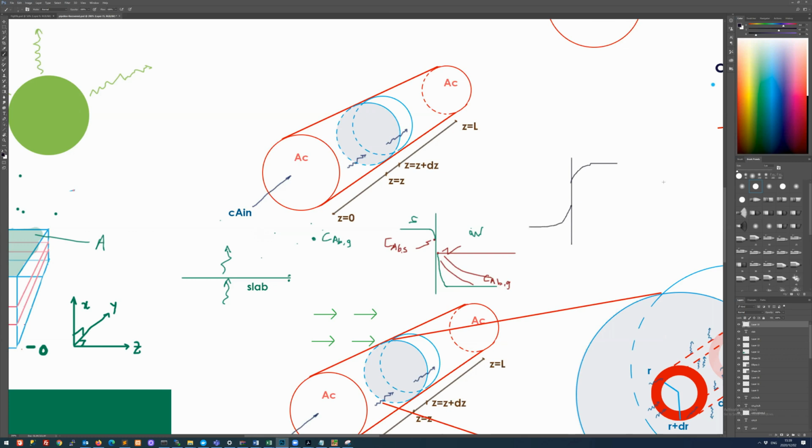So this is the position R, and this is going to be the radius of the particle. If you look at the particle, let's draw it here like this. R equals 0, we have a condition here, and then at the surface, you've got this SO2 out here trying to diffuse its way in. Just outside here, there's the gas concentration. There's a discontinuous jump to the concentration inside the particle, and then there's diffusion inside here.